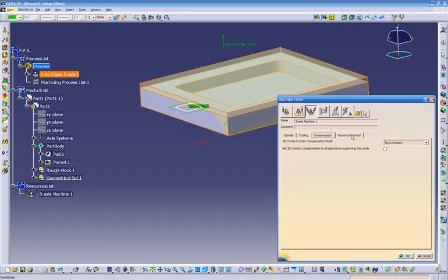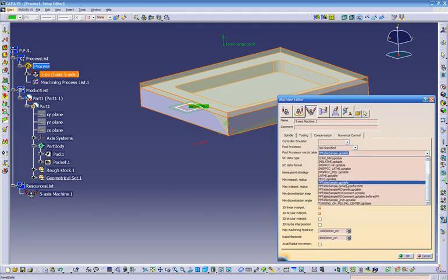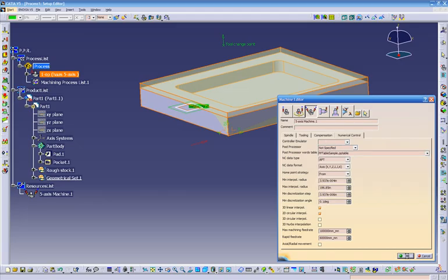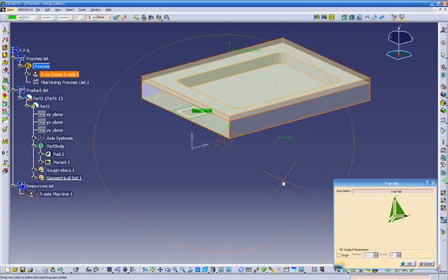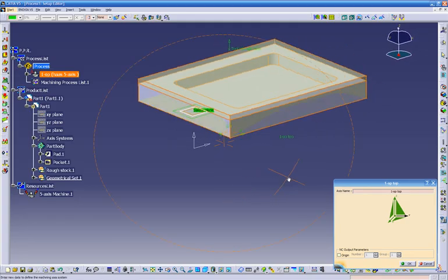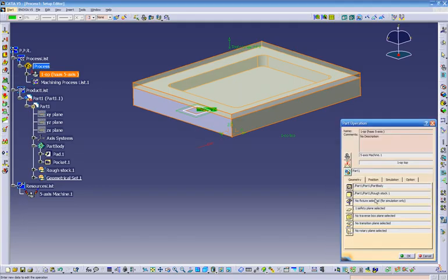If you use a color compensation and your PPT table, you have to choose it right here. Over here is our machine, and over here once again is our axis. If you have your own axis or a different axis, make sure you click on this area, highlight your axis, type the part number or operation number in here, and click OK.